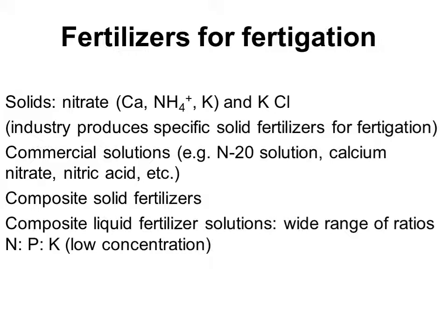But the industry produces solid fertilizers with higher levels of quality in terms of purity than those used for normal solid fertilization. Purity is important because the impurities might create problems of clogging of the drip emitters in drip irrigation.